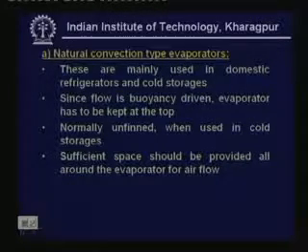This is very important, just like your condensers, flat back condensers or wire and tube type of condensers, you are relying on buoyancy effects for airflow. So the delta T's are not normally very high, so the potential for the airflow is generally small. So if there is large resistance, then the airflow gets affected adversely. So if you want to have good airflow, you have to provide sufficient space all around the evaporator so that air can flow with minimum resistance.